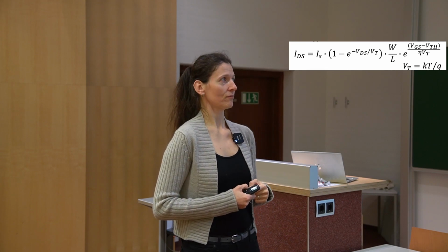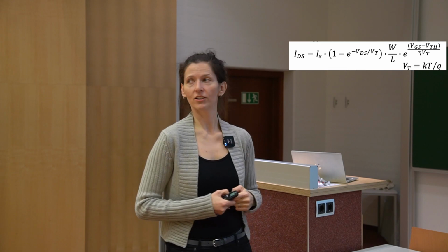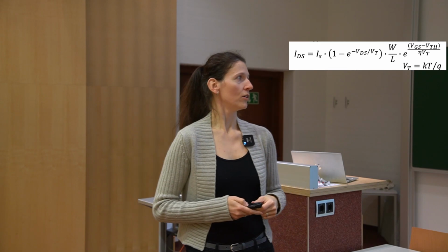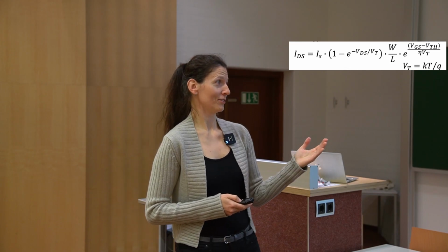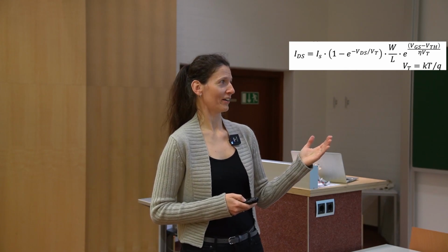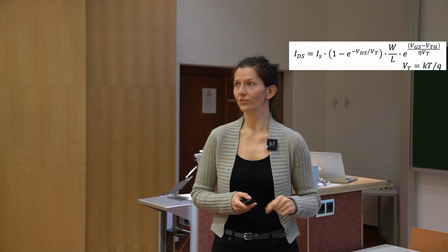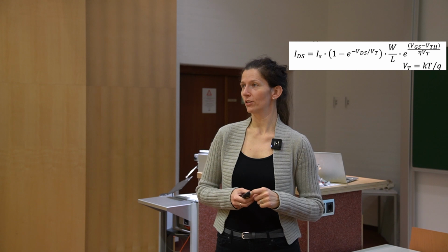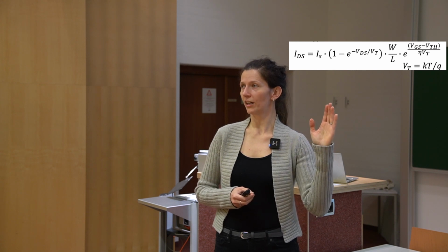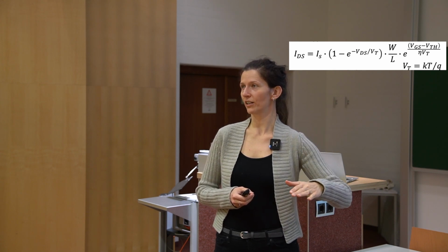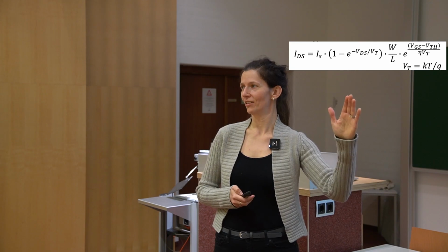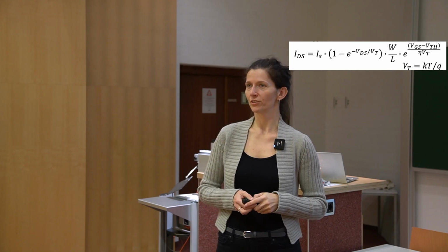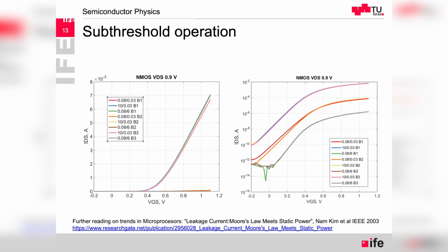And the charge carrier transport is based on diffusion. So that's why also in the subthreshold, when we look at the characteristics, they are linear, and a diode, which in forward bias is also dominated by diffusion. If we take the logarithm of the current of the diode, plotted as a function of gate to source voltage, we also have this linear behavior. And that's because in both cases we have the diffusion current dominating the charge transport.